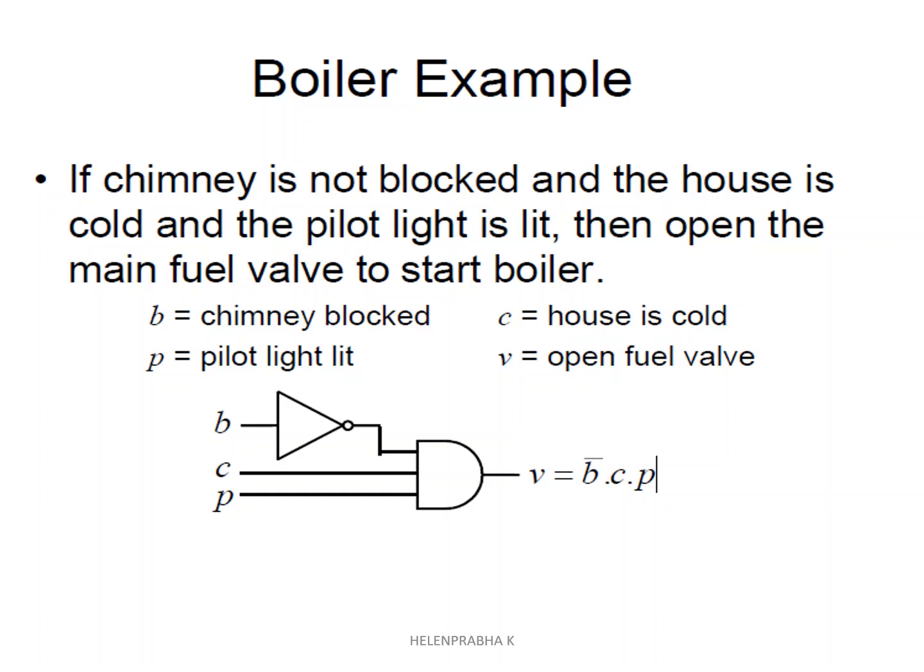So we can write any real-time statement or real-time application in the form of a Boolean expression. Using Boolean simplification, we can minimize the expression and use the gates based upon the expression. Why are we reducing the expression? If we didn't reduce it, we would require more gates. So Boolean reduction is important. If we reduce the expression, we get a simplified expression, we can use minimum hardware, and it will reduce the cost.